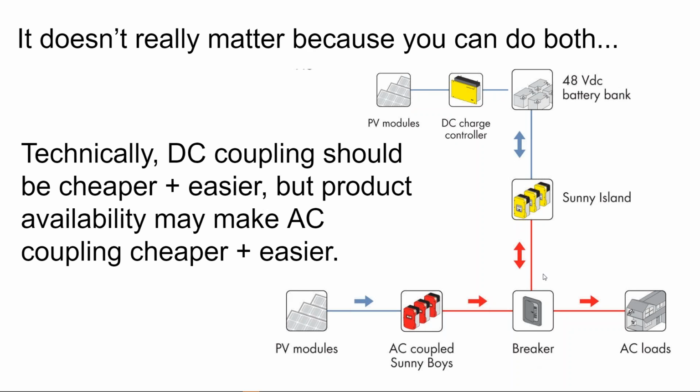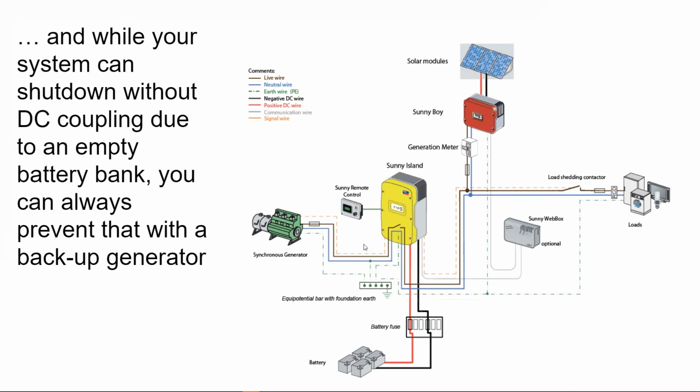One solution is to have the battery inverter not fully discharge the battery, but to hold on to a reserve capacity so that in the morning it can start the solar array back up. Another solution is simply to add a generator so that when the battery voltage gets low, the generator turns on and either can function in tandem with the solar array or charge the batteries up, or wait until the sun comes back up and provide the grid signal for the solar array to turn on.